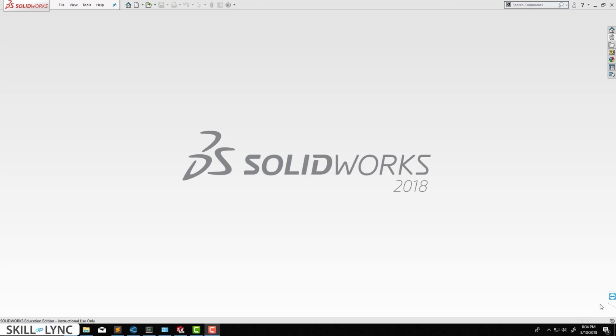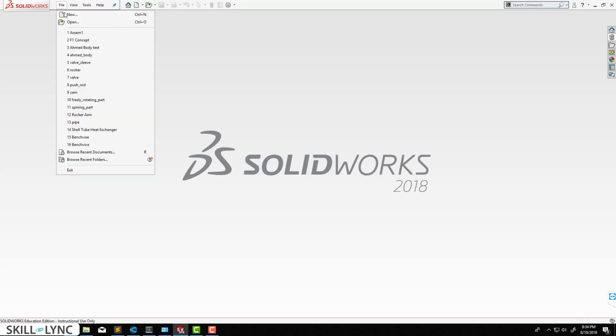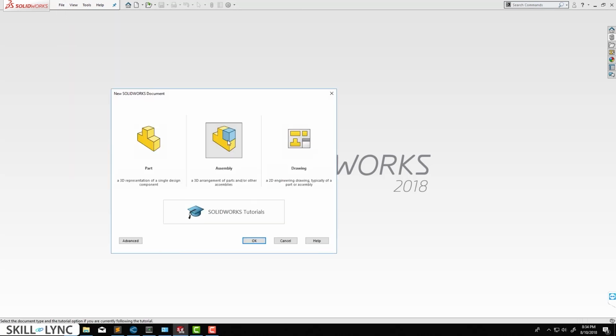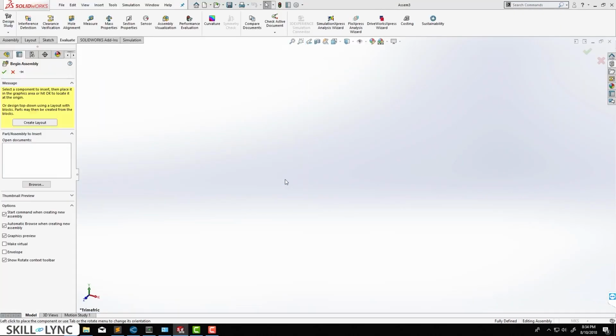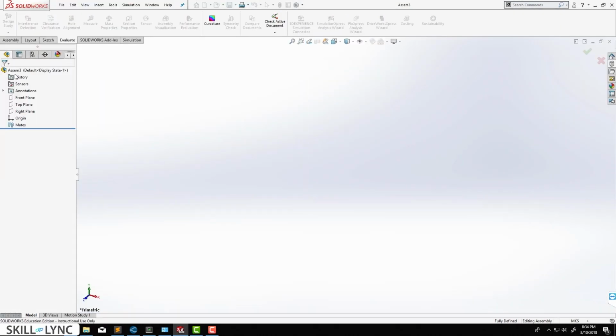In this video, we will be showing you how to create the planetary gear systems using Solidworks. So click on File, New, and then directly go to Assembly. Click OK. Now we are not going to be importing any new parts, so let's just close this. And we are going to get started by importing a ring gear.